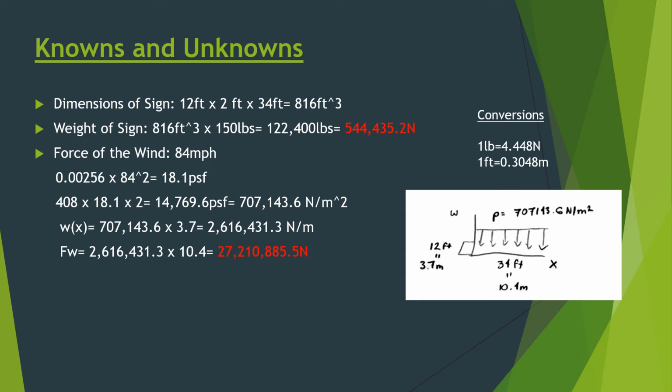And then I used another equation that has the area of the surface the force is going to act on, times the pounds per square foot, times the drag that it's going to have. So I have the pounds per square foot and I turn it into newtons per meter squared. So I went back to one of the problems that we had in our homework that was of distributed loads. And as you can see in the picture to the right here, this is the answer that I got.